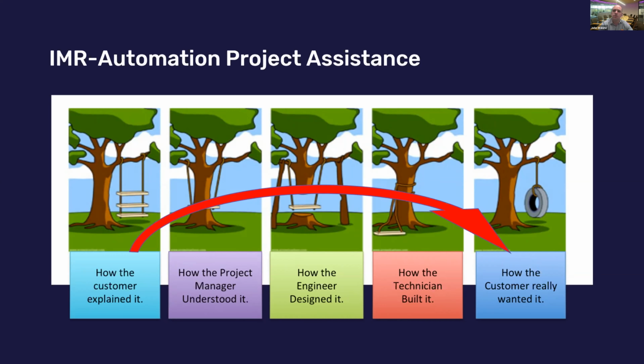But the solution required operators who were trained and competent in the use of the pendant, which was a small percentage of the operators. And this led to hours of downtime waiting on a trained operator or someone who had confidence to switch modes. What IMR's experience brought to that project was to ask for a mode to park the robot and to allow manual tending of the machine. Therefore, a simple button press in the machine interface would activate a mode where the robot arm would park in a position to allow operator access, reducing the skill required to switch modes and increasing the availability of the machine.